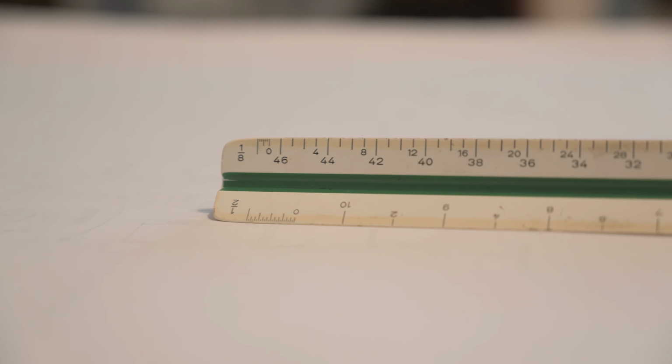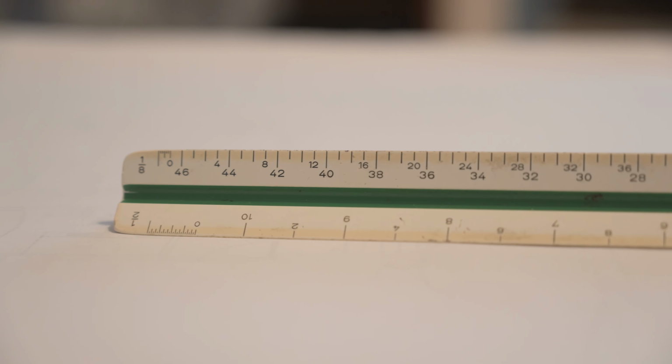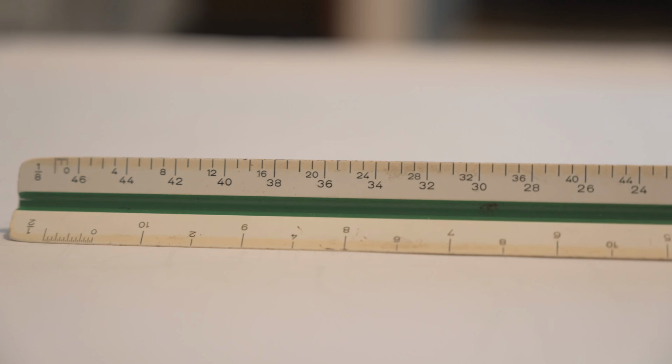From this side is 1/8 of an inch. So it's a little bit confusing if you don't understand. And as a contractor, when you're on the job, you can take a tape measure and just go, in this case, 1/4 inch equals a foot. You can take your tape measure and match up the same way. So every 1/4 inch is going to be a foot.